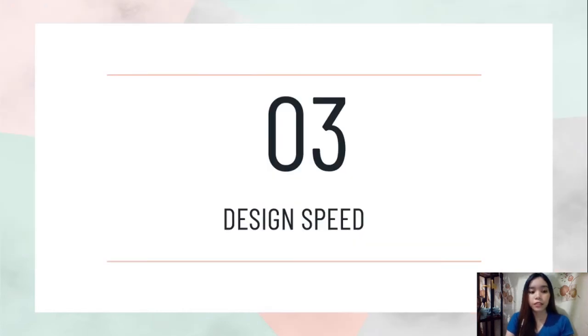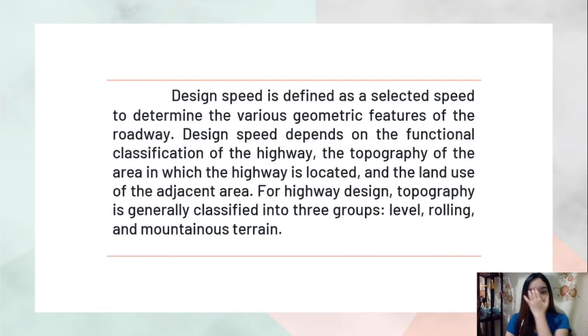Then the third one is the design speed. Design speed is defined as a selected speed to determine the various geometric features of the roadway. Design speed depends on the functional classification of the highway, the topography of the area in which the highway is located, and the land use of the adjacent area.